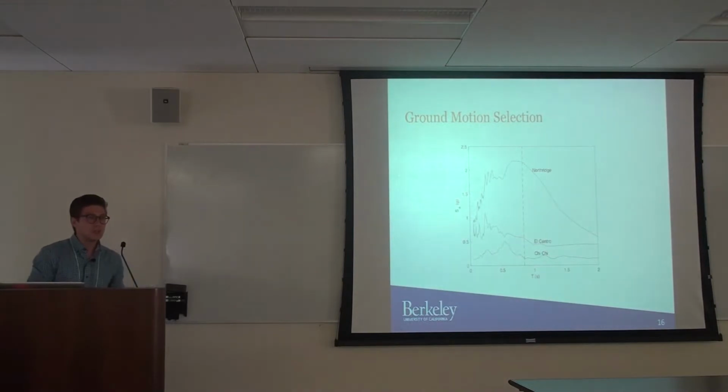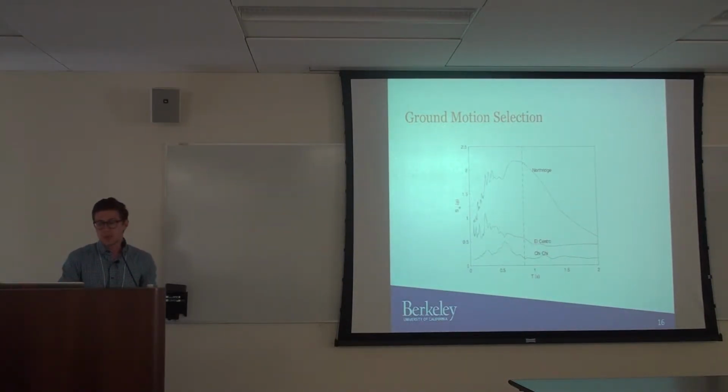For the test itself, we looked at a lot of ground motions selected using Jack Baker's method, and we selected 3 representative motions of a minimum, median, and maximum level motion. So Chi-Chi, El Centro, and Northridge are the motions that we went with for our specific structure.